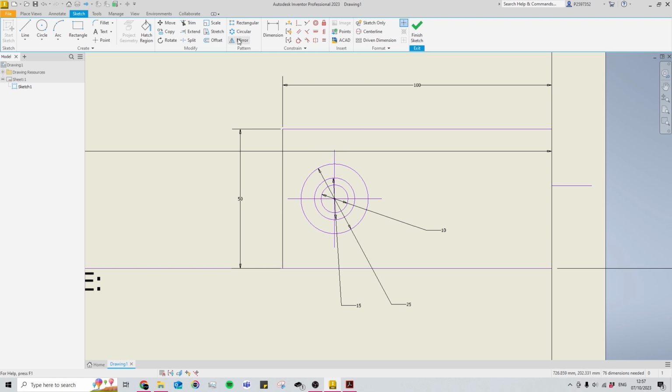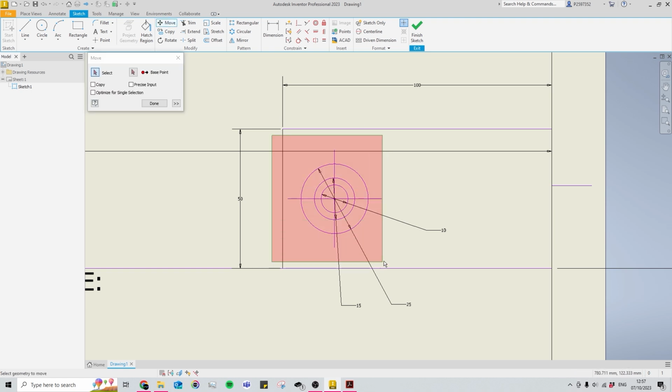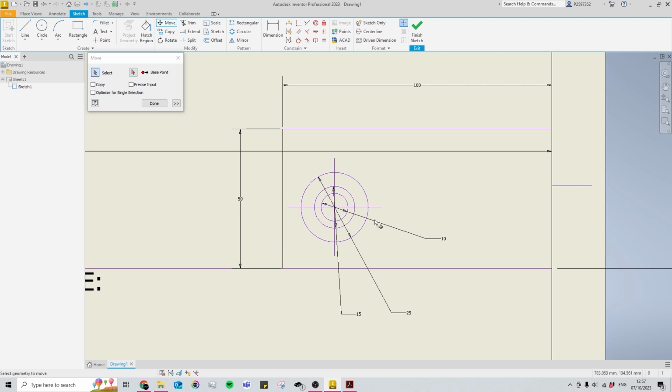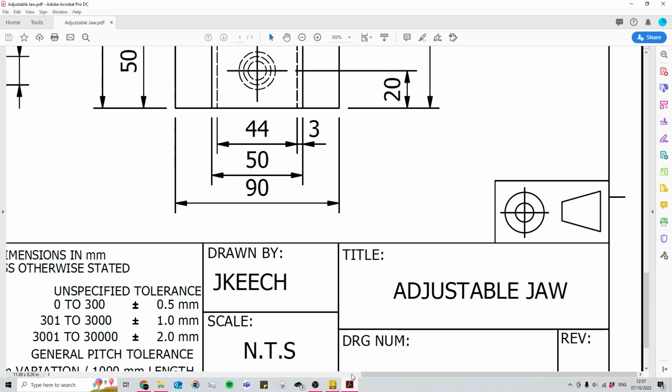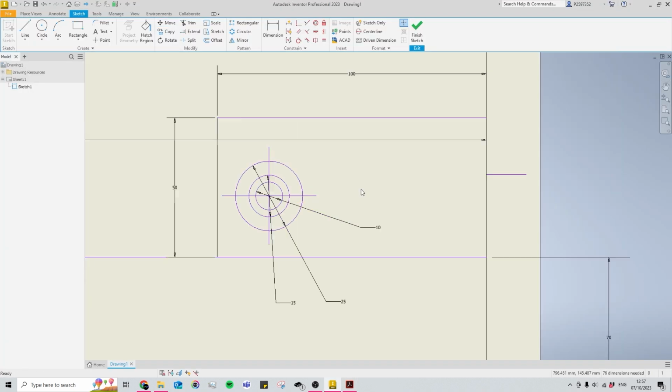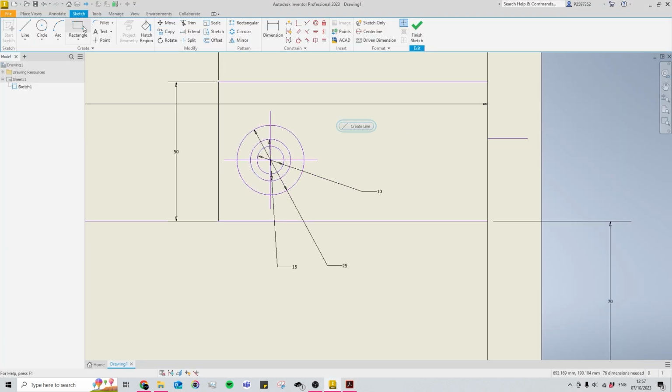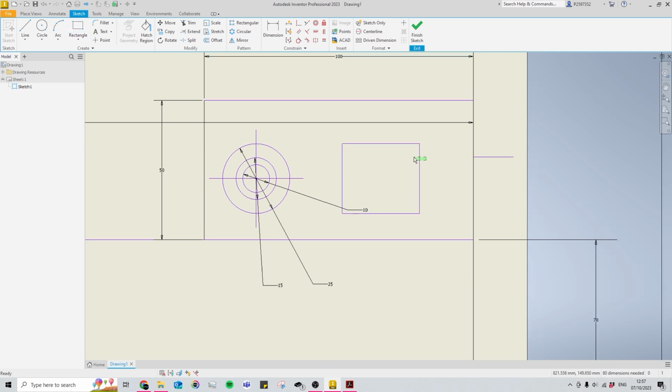And the same goes for just here, 5 mil down, 5 mil up, and connect them together, delete the small ones. Now here my symbol has gotten too far up, so we're just going to bring it down in a more central position. So there's our target. Now we need to draw our parallelogram. Now this one should be a lot easier. I'm just going to start with a rectangle that is the same size, and I'm just going to take these corners, come in here and delete all the restraints.